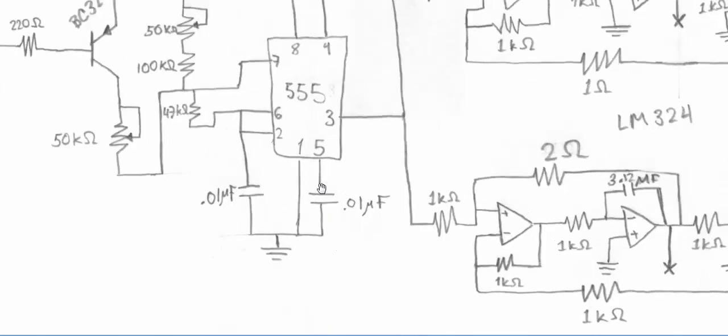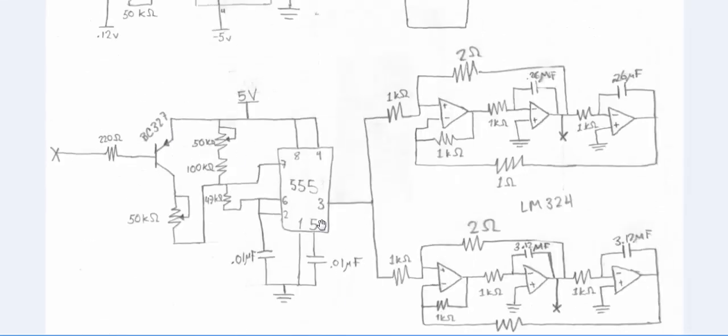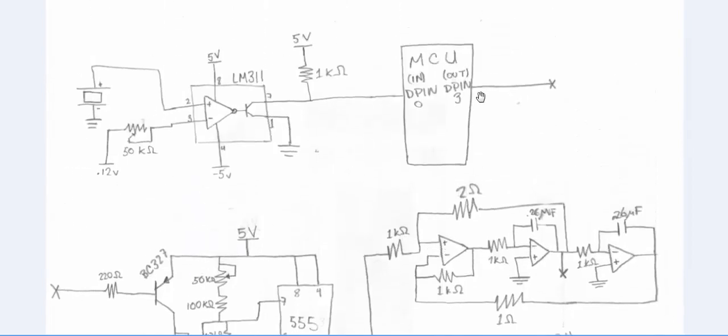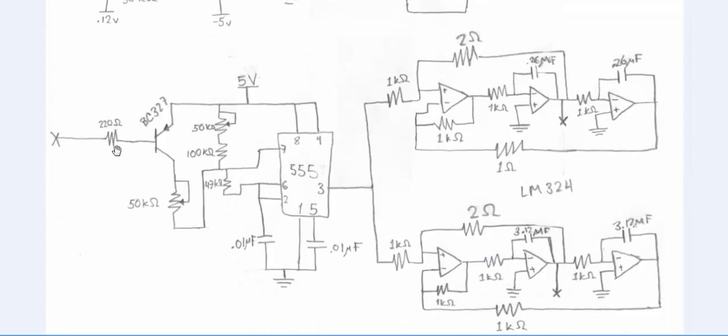Now this is the modulator part. From this part we have a digital signal that goes 1 and 0 at the frequency at which we send the data, 150 hertz, so it goes here. So now we have a modulated signal that oscillates.